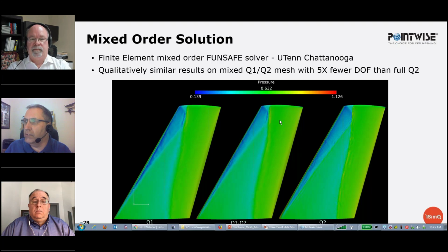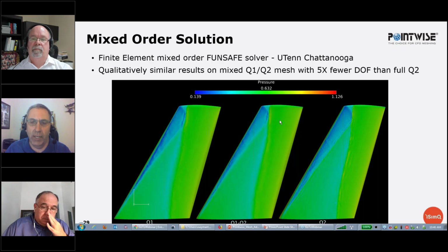The nice thing about the mesh adaptation scheme that we have presented here is it's largely orthogonal to the choice of the mesh that you take. The mechanics of generating the sensor that we've described are going to tell you the deficiency of your chosen mesh style on your chosen solver, because you're using your solver's output to tell you what it believes the mesh quality is with respect to the solution.